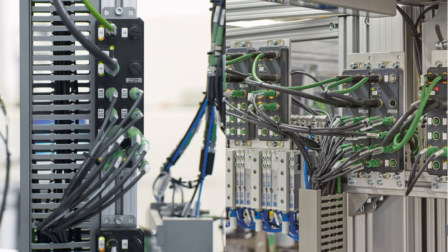I could just use all pre-purchased sensor cables, plug them from the sensor to the I/O device, and then I'll do pre-made power cables here to power the devices. And these are actually Ethernet cables. This is an M12 Ethernet standard that's used for Ethernet devices in the field. And we're actually using that daisy chain concept. We're daisy chaining the sensors together. So you can make the leap to this.